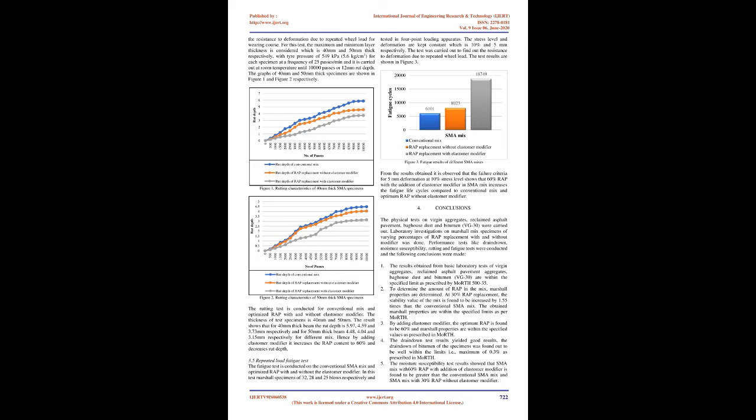The main factor leading to premature failure of the bituminous pavements is due to the presence of moisture in the pavement surface and the inability of aggregates to retain the coating in the presence of moisture. Hence, it is important to conduct tests regarding moisture susceptibility.